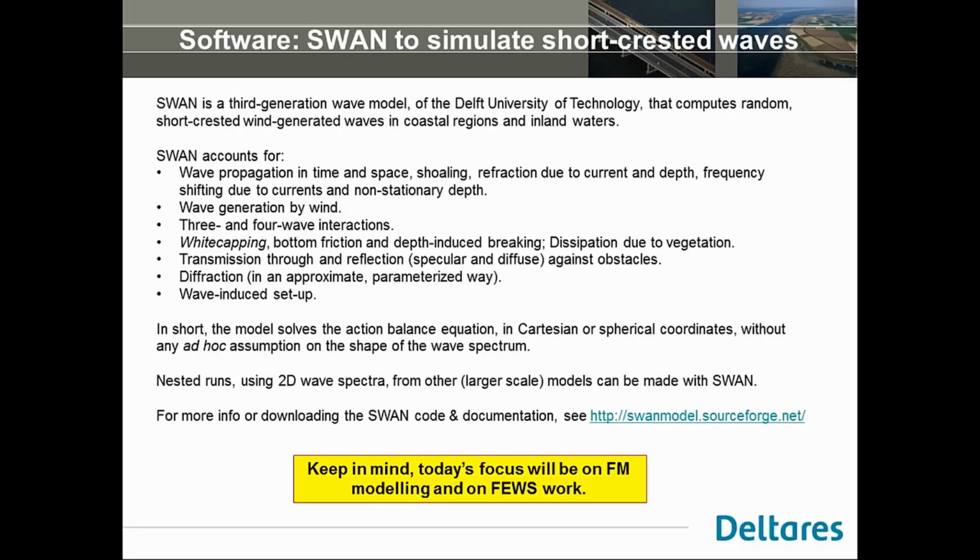Last but not least, we also use SWAN, developed here by our neighbors at the Delft University of Technology, also open source. We use this to simulate wave propagation and generation, but also wave setup, as I will discuss a bit later. So SWAN is quite handy for these kinds of applications in a coastal ocean setting.